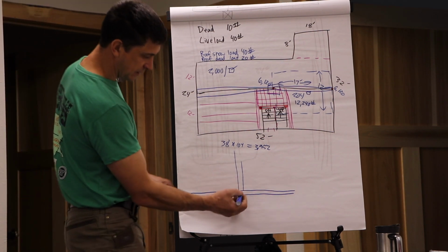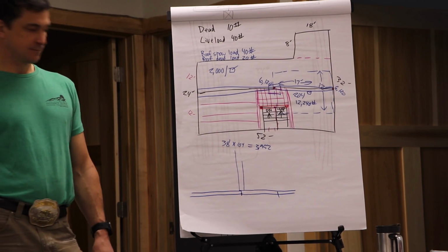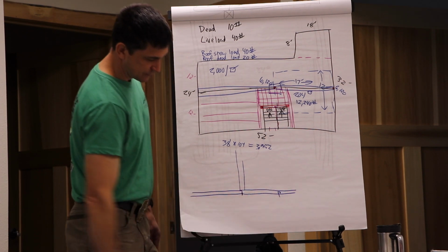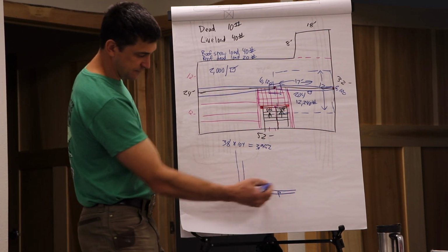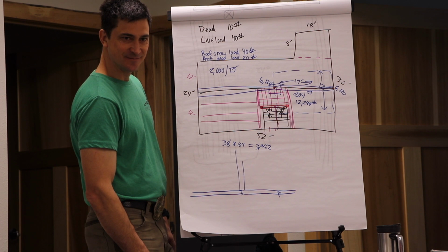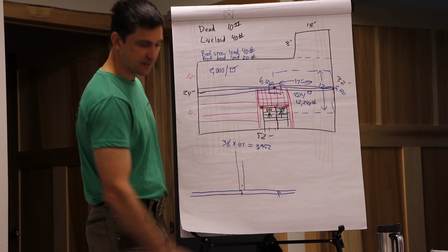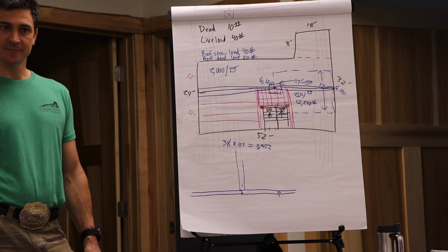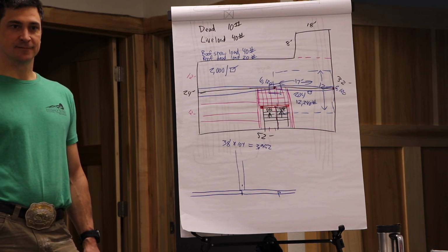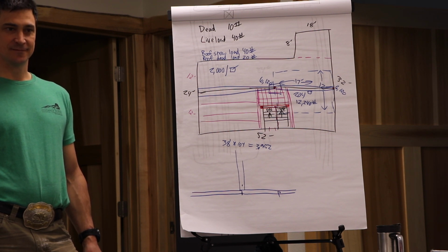Okay, so if I put that mark here at 16, which side do I put the X on? Okay? Then when I run my sheeting... No, the X would go right in the middle of it, or you'd have to move your line. No, because he's already halfway through. You don't have to do anything. It's already 16 inches over. Well, set it where the mark is. If the 16 mark is on it, you're covering up the mark again. That's what you're doing, you gotta move your line over. You have to add 3/4 inch and mark it on the other side. Add or take off 3/4 inch.